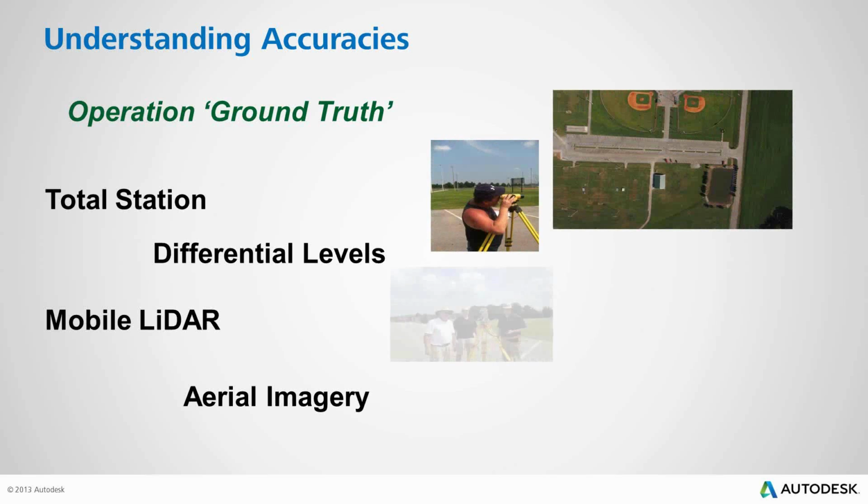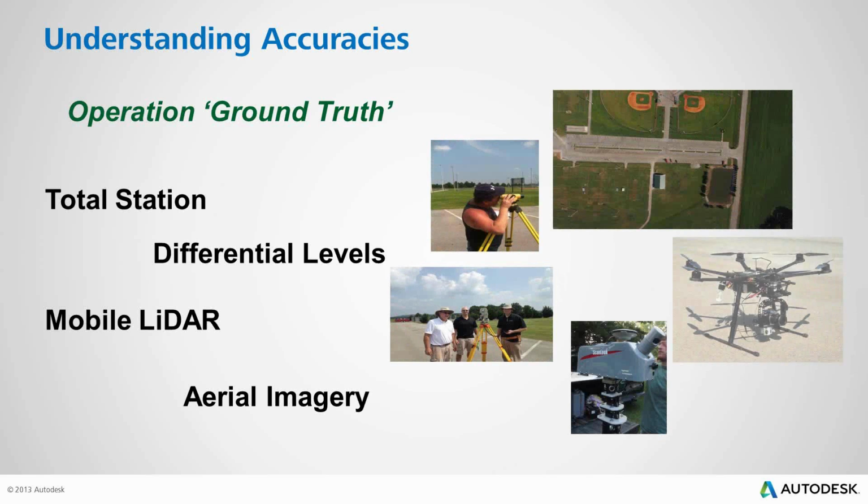What about accuracy? A quick overview. We did a ground truth test for the accuracy, comparing LiDAR, so laser measurements with total station, with measurements from UAV and the camera. Something I forgot to mention, of course, is that in the photogrammetry process, at some point you will need to give a scale to your 3D model. Either you do this by adding survey points into your photo to 3D process, or you can also add a simple reference distance in order to scale the scene.